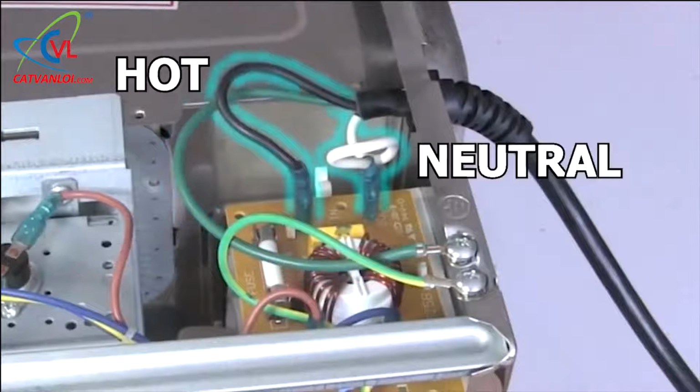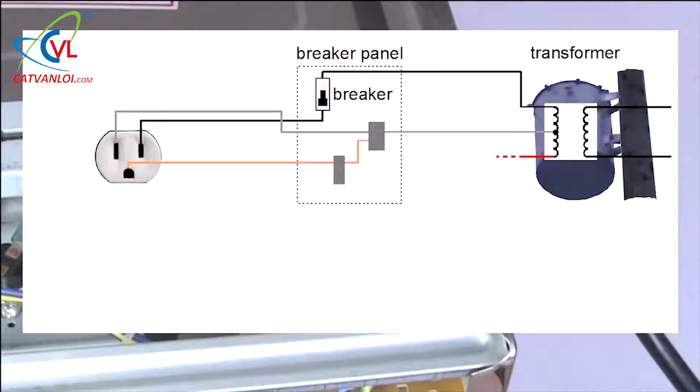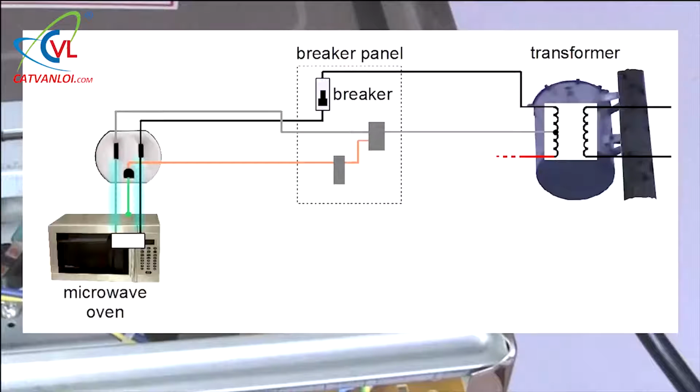As we said, the electricity flows through the hot and neutral wires. The third wire is the ground wire. The ground wire is connected to the metal case, and normally no electricity flows through it. We'll add the microwave oven to our diagram. The hot and neutral wires go to the electronics, and the ground wire connects to the case. But the case is not connected to anything else. Electricity won't flow on it because there's no return path.